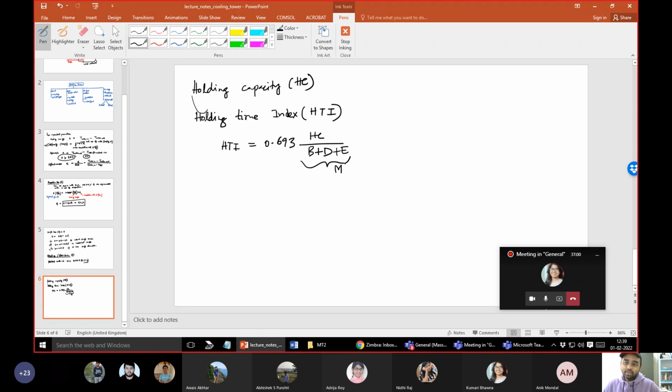as possible, right? That depends, as I said, on the chemical treatment program or chemical treatment technology that you are using in your system or in your plant, so that this holding time can be improved, and accordingly the maintenance schedule, the makeup water, circulation rate, etc. are decided, right? The cycles are all fixed based on how efficient these chemicals are.